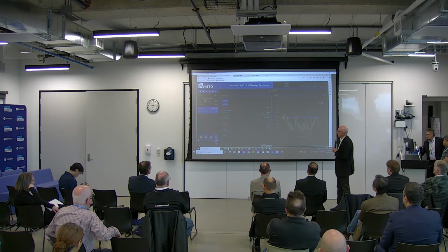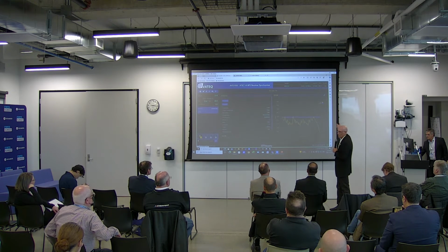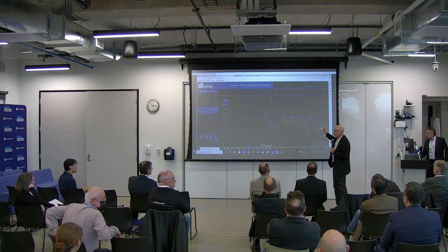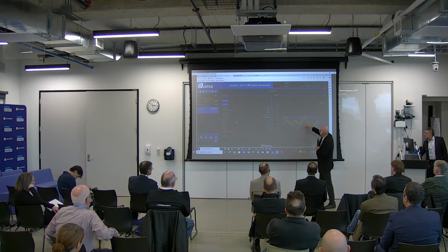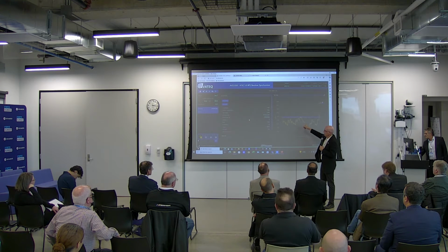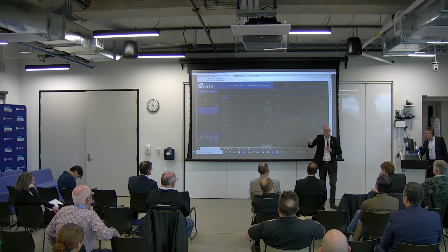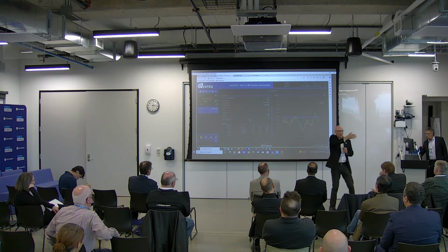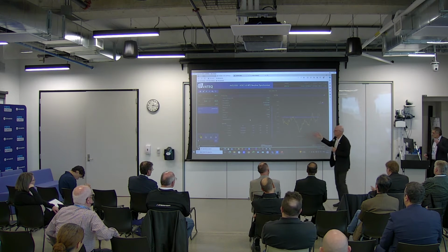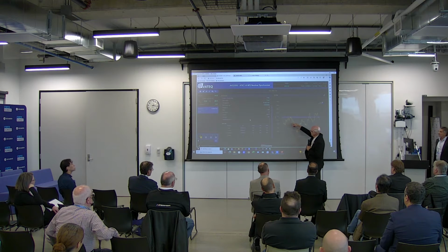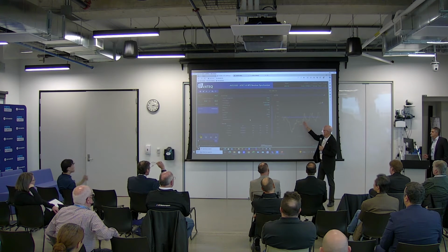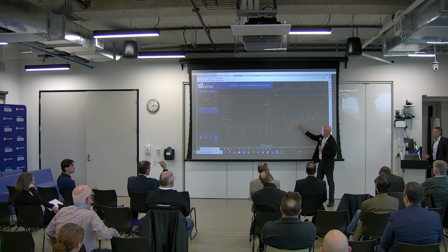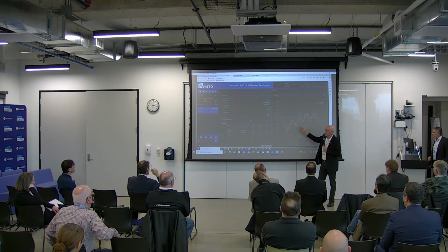Yeah, so this is the synchronizer. This is out 1.5 kilometers away at the transmitter site. This is basically the jitter. This is the measurement happening when, as Tariq described, you have the first symbol coming off of the transmitter, and you're measuring that, and this is the measurement of that transmitter, the time of arrival of that signal, of that bootstrap, compared with a reference time.